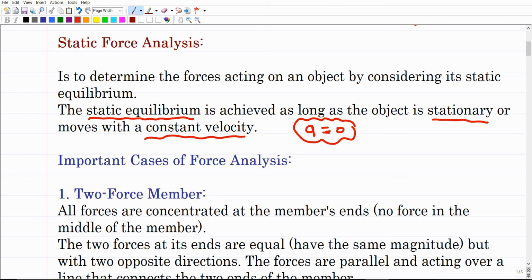It is typically the same thing that we used to do for the position, velocity, and acceleration analyses that we discussed through this course. We said that for the position analysis, you are limited to just two unknowns. These two unknowns will be magnitudes or directions of different vectors, or even the same position vector, the same thing for the velocity and the acceleration. So to find these unknowns means that you are already doing analysis.